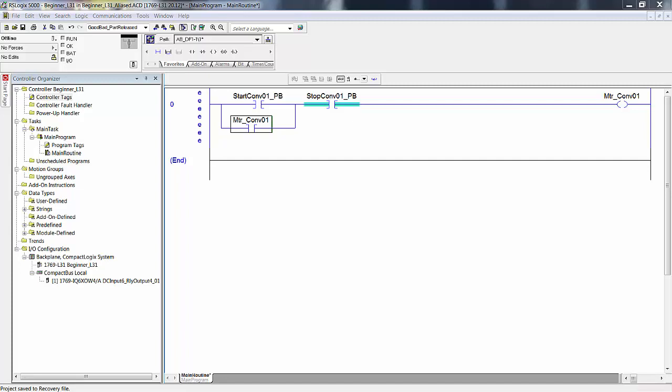But it would be much better if before the I/O was even assigned, meaning before the I/O sheets were even drawn, that you gave a list of the I/O needed to whoever is actually drawing up the design of the control system, drawing the configuration for the I/O, to show them what you need and let them then follow your list. What we're suggesting is that the dog wag the tail, not the tail wag the dog. And I'm sure people who design control systems feel they're the dog and the people that program, they're the tail. However, whatever the designer does, the programmer is stuck with it.